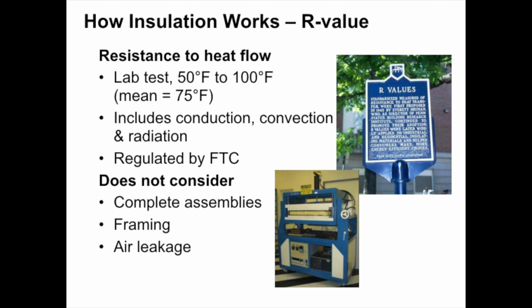Because most insulation materials aren't completely solid, the R value actually does include all modes of heat transfer. So conduction, convection, and radiation, anything that might occur in the material is actually measured when we determine R value. And any R values that are published by insulation manufacturers are actually regulated by the Federal Trade Commission through what's called the R value rule.